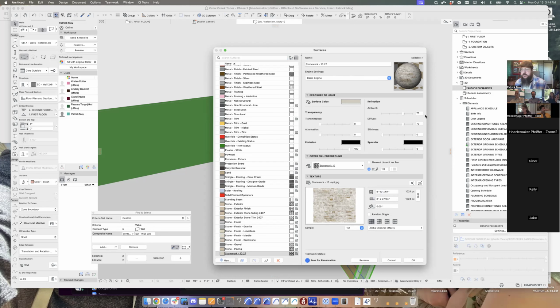There's sort of a magic number for the reflection settings here to get it to be more of a matte to semi-gloss finish. Otherwise, they end up either really washed out or really dark. And that number combination is 85, 85, 10, and 12. I can't tell you how I came up with that number, just trial and error, trying to match, I think, Benjamin Moore paint codes or something like that. And that's what shows up best on 4 and 5K resolution screens, that number combination with both emission and specular glowing set to black.